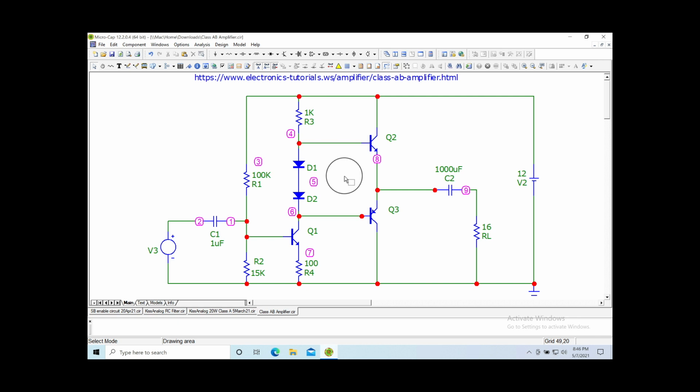They should be on. Now, we might want another resistor in here, a pot in here, to turn these transistors on a little bit more to adjust their bias. So that might be something we want to do, because with this setup, we're kind of stuck. I mean, hopefully these diode drops are going to equalize or be a little bit more than these and be able to turn them on. And then when this transistor goes up and down, he's just shaking both of these bases up and down with them. Okay, and then this point here is just going up and down. So hopefully there's enough current going through here to drive this.